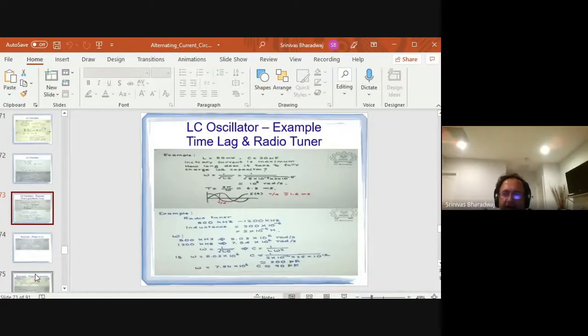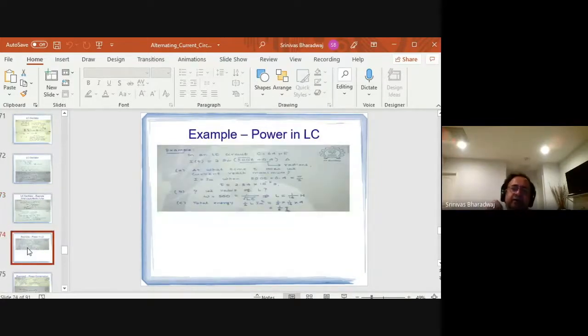You have it in a radio. When you turn the radio, you adjust either the capacitor or the inductor so that you have resonance at a particular frequency. Then you will hear only that frequency. You want the quality factor to be very sharp at that particular frequency. When you rotate it, it adjusts the LC resonance, so you have one sharp peak here or there, and correspondingly you end up with a different resonance point.